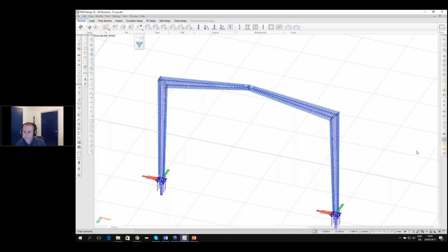Giuseppe, I'm not completely sure what you mean here. There are two ways of doing these. If you do bars, and you do first order, you need to have your buckling length. But if you do it like this, you don't need buckling length. You need a stability analysis to see all your column effects and all your buckling, your lateral torsional buckling problem. It will give you all the lowest values for this. So you have a stress analysis and you have a buckling analysis. That's two different things.